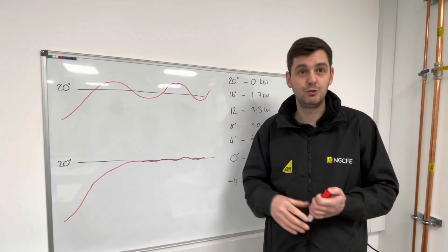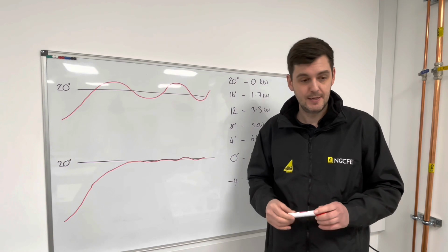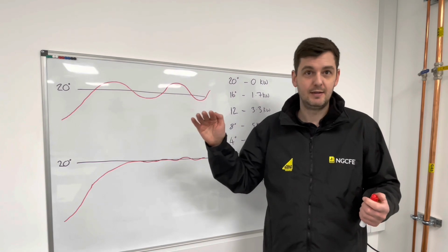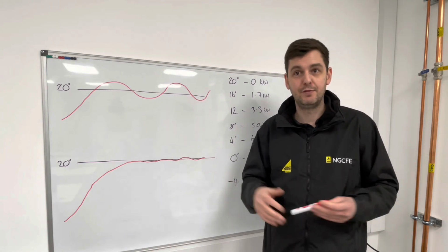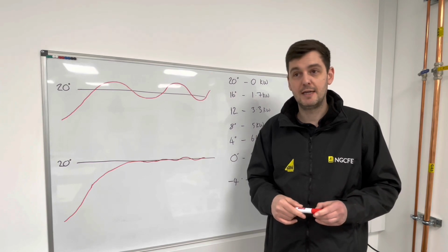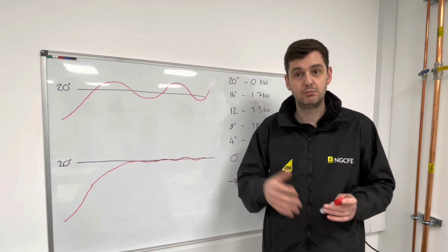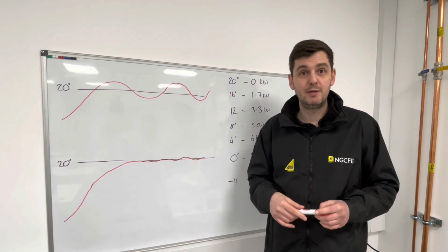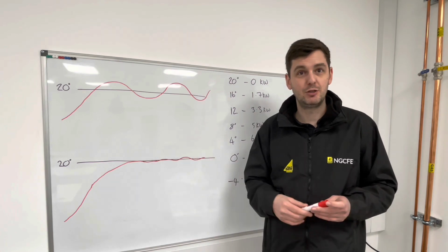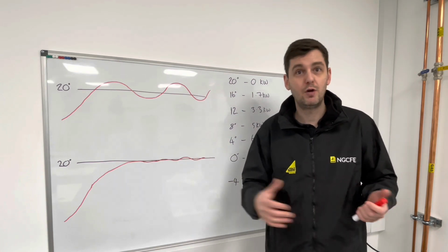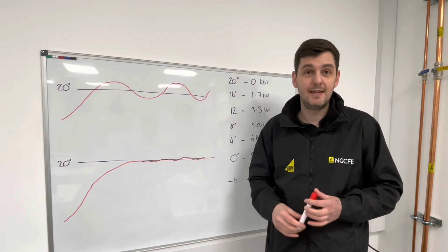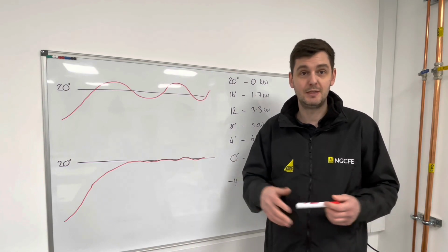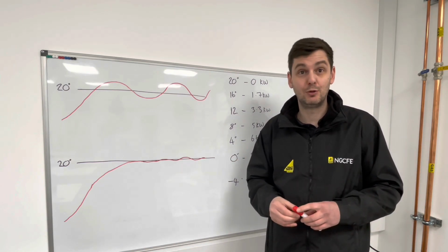One solution doesn't fit every type of customer. For something like an air source unit, it is desirable to have a slightly lower setback temperature, again 3 or 4 degrees. If you've got a system where your customer is at work for large portions of the day, you may not want to look at weather comp. It might not be the best solution for your customer. Something like an on-off control might be better. But again, it depends on the technology, the insulation of the property, the mass of the property, all sorts of different factors, and also the type of customer and how they live.